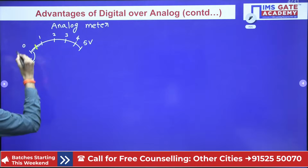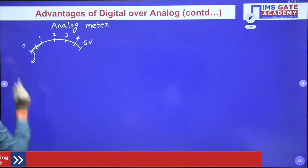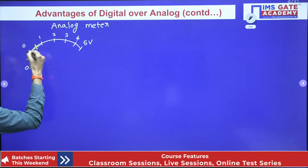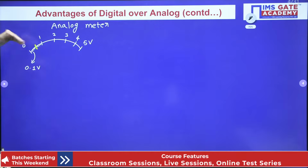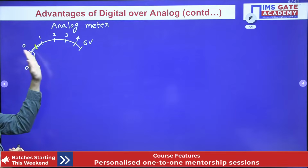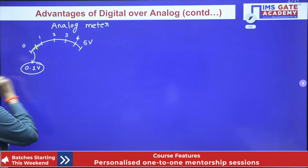Between 0 to 1, I have considered 10 small divisions. So the first small division value will be 0.1 volt, because here the range is 1 volt, and within that I have made 10 intervals. So the first small interval is nothing but 0.1. So if the meter is exactly pointing to the first small division, you can note the value as 0.1 volt.